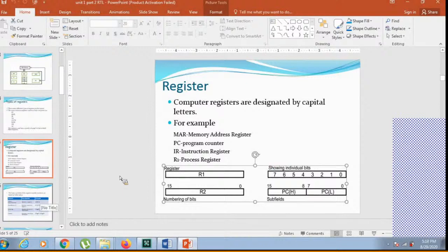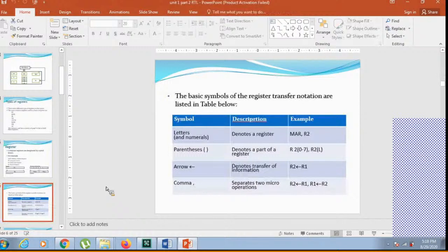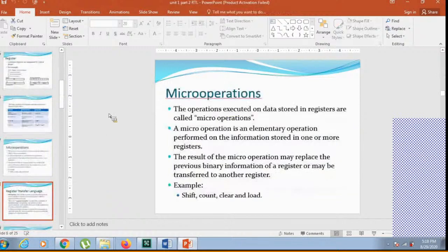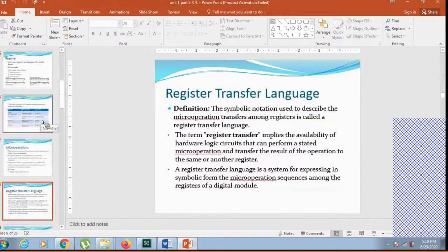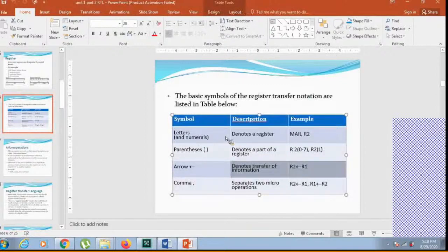Register transfer language will move the content from one register to another register so that the previous content will be erased and new content from the other register will be placed. Generally, it is represented using a replacement operator. How does a replacement operator look? It is a reverse arrow mark. The register transfer will happen from the right hand register to the left hand register. And always the transfer happens bit by bit.